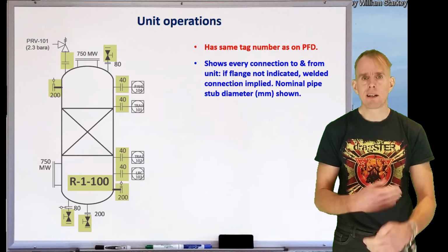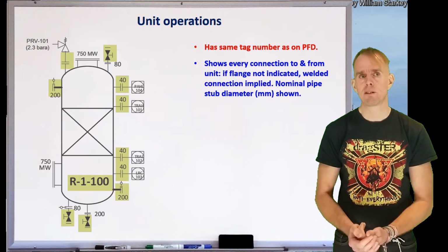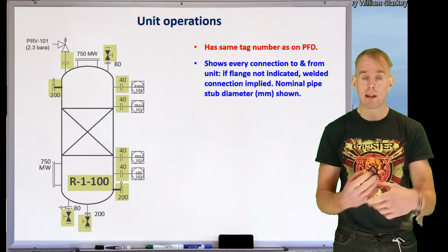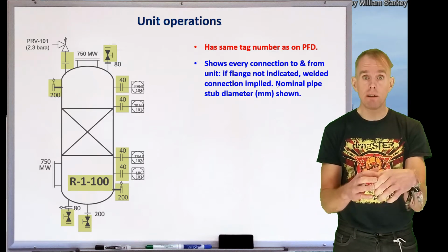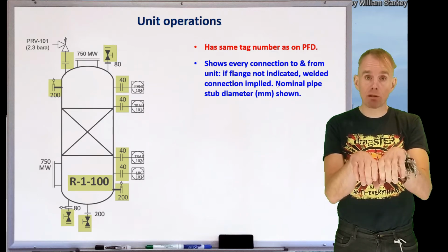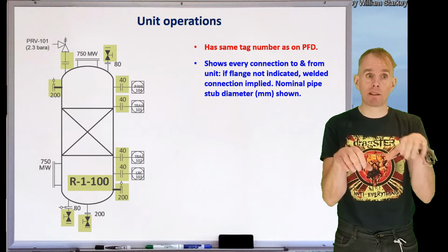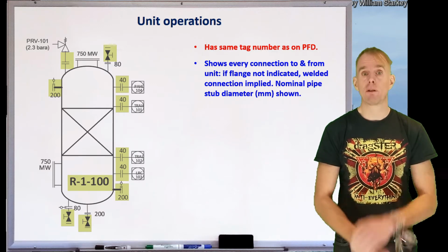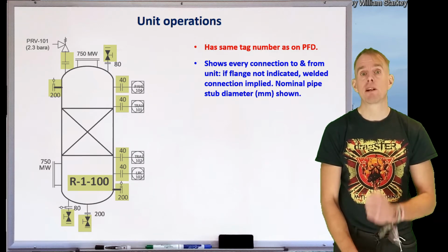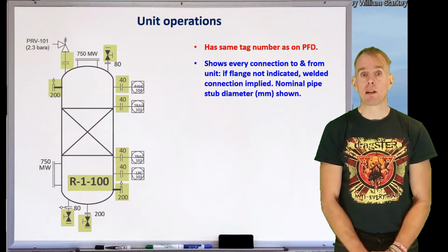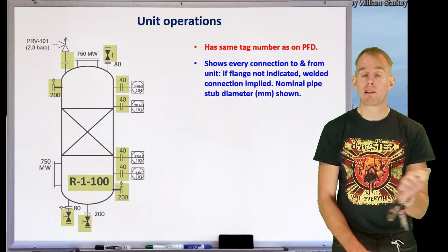So if we're going to connect additional items of equipment into a vessel, it needs to be done through a flange. So this is a bolted union in which you will get your instrument, you'll bolt it to a pipe stub, and that pipe stub will be welded to the vessel. Those two parallel lines that I've illustrated on each of the instruments represent the presence of a flange. And if those two parallel lines are missing, it will imply that the entire section is welded.